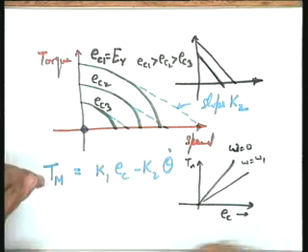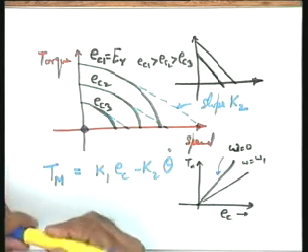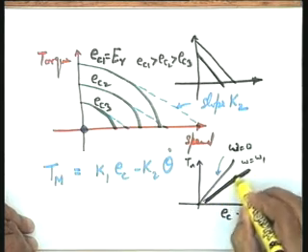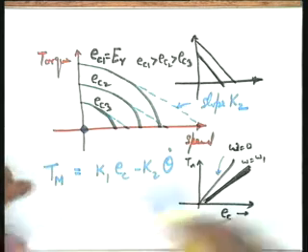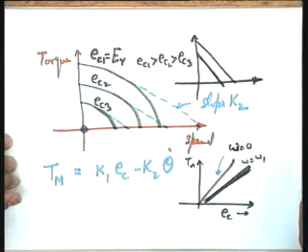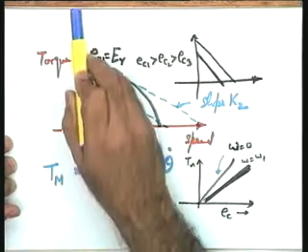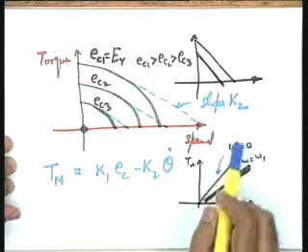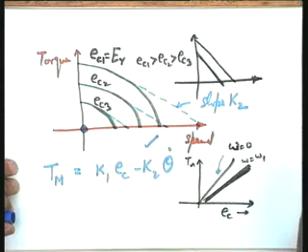So in that particular case, what is K1? K1 is going to be the slope of this particular curve. They will be more or less linear in a linear model, but however this is an assumption, the linearity assumption we are taking up for a nonlinear device, which we know is true for a restricted range of operation. So if I plot control phase voltage versus torque, taking speed constant, I get a line whose slope gives me the value of K1. K2 is directly available to me, and therefore this becomes the equation for the torque developed in the case of AC